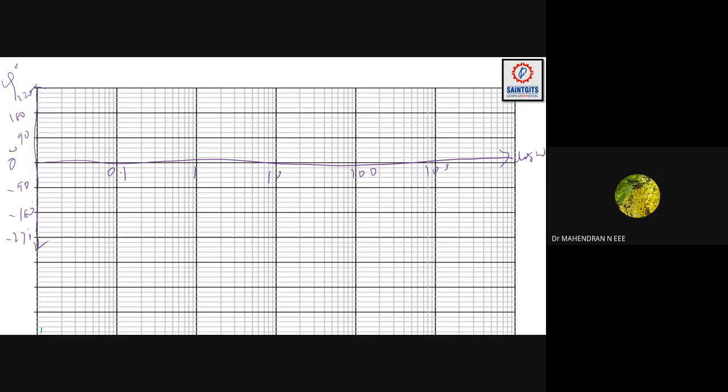It's a constant. So when we are projecting a constant into the phase plot, it is nothing but the origin. So here this is term one, projected to the phase plot. The next term is 1 divided by 1 plus s divided by 50. Am I right? So if you're talking about 50, 50 divided by 10 is 5, and 50 into 10 equals 500. So you mark these two points first.